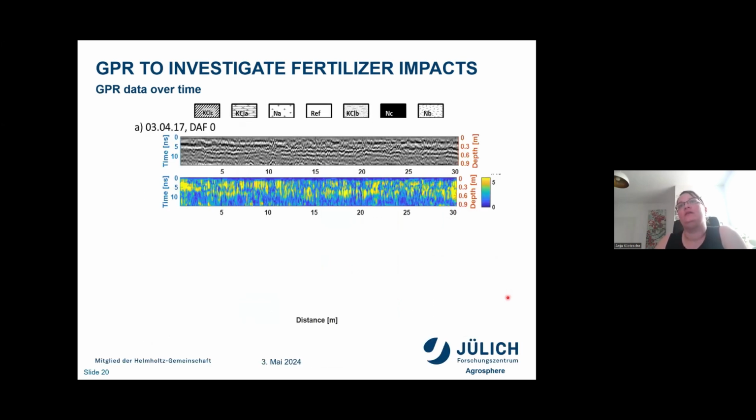And then when we look at the GPR, unfortunately we don't have that much data for GPR because it's not the best soil for GPR, and also it's maybe not the best idea to look at changes in ion concentration, because ion concentration is more attenuating our GPR waves. So it's actually not the first instrument you would think of as a geophysicist to be used.